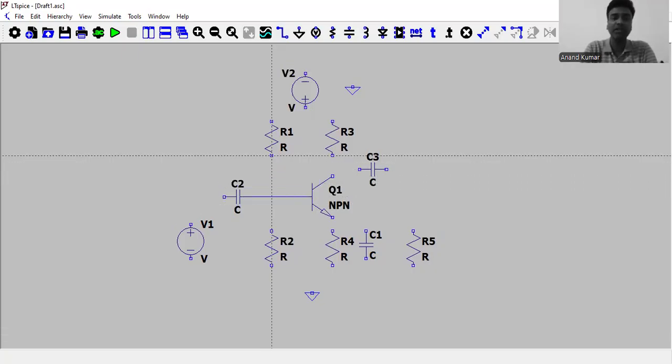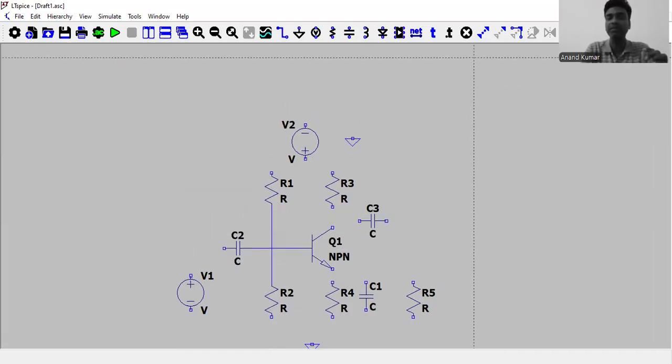So unfortunately, some students might make a mistake like this. They click on R1 and might directly connect it to R2 by mistake. It means that resistors R1 and R2 are connected, but not connected to the base of the transistor. If the base of the transistor is connected, a solid square icon will appear here. If it is not appearing, it means some wrong connection is there.